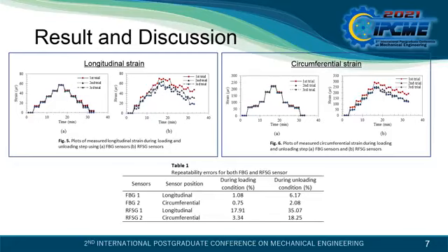However, the pattern of RFSG as shown in figure 5b is not truly consistent within the 3 replication trials, and a high hysteresis response is observed which is not detected by the FBG sensor. So the RFSG sensor generates much noise compared to the FBG sensor, which significantly influences the data precision of the RFSG sensor, especially when the strains are relatively small.